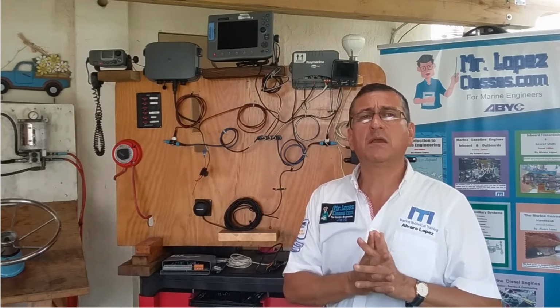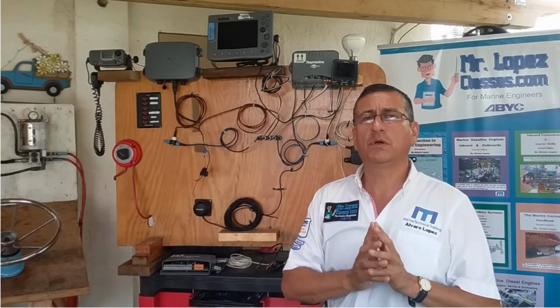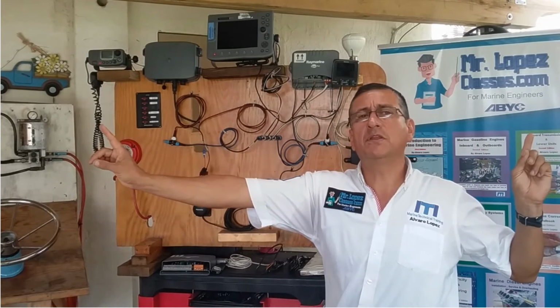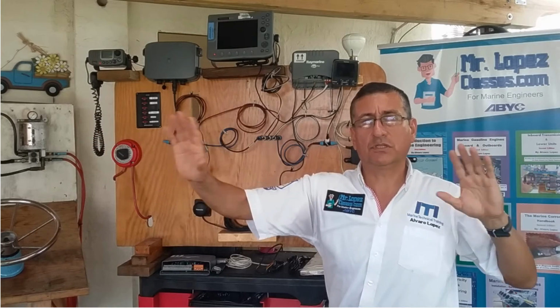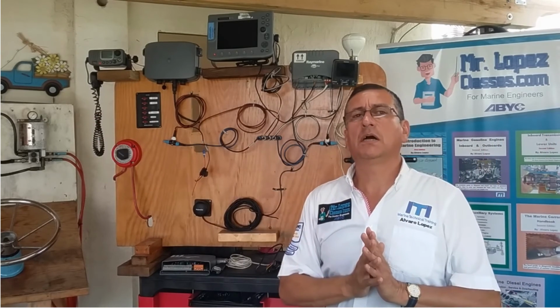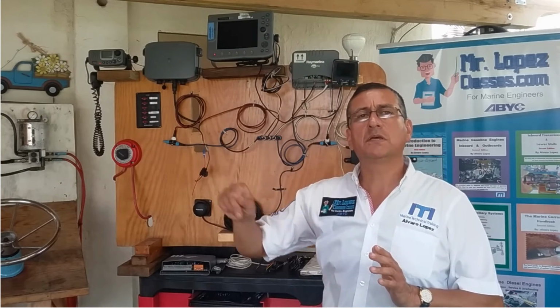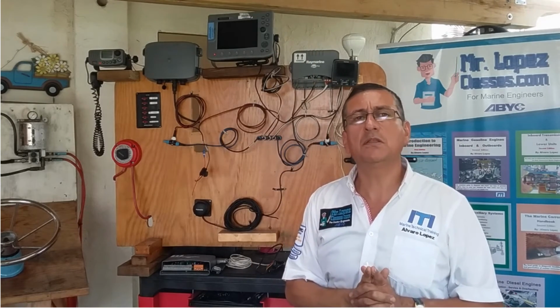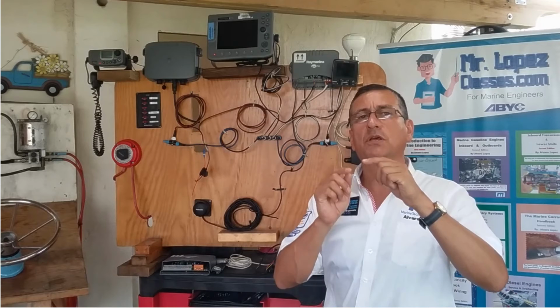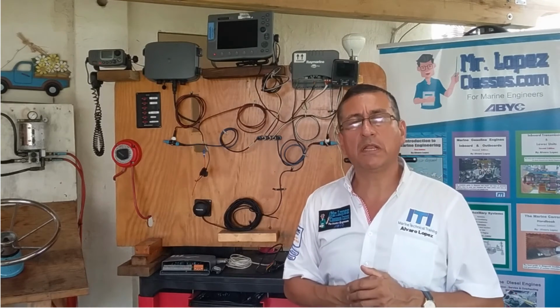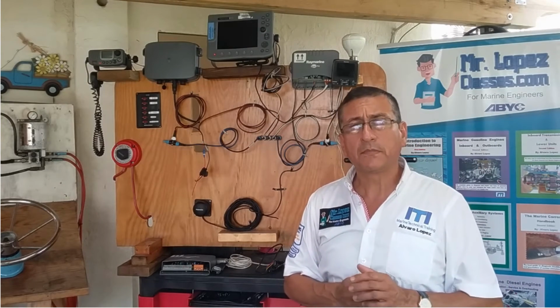If it's mini cable or mid cable, we are going to use 250 meters in between resistor and resistor, the total distance. And the total cumulative drop lines, no more than 78 meters. The maximum distance of each drop line, 6 meters.